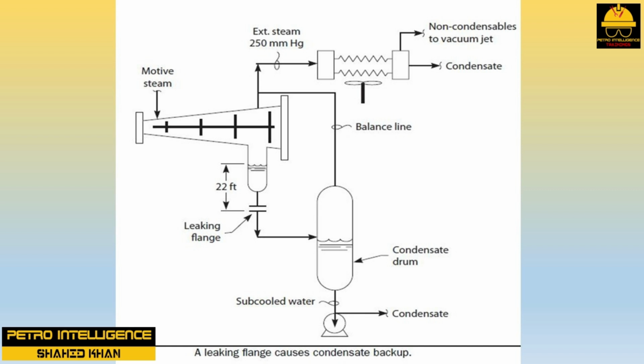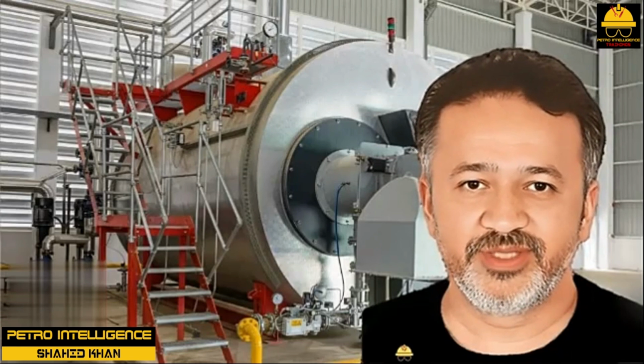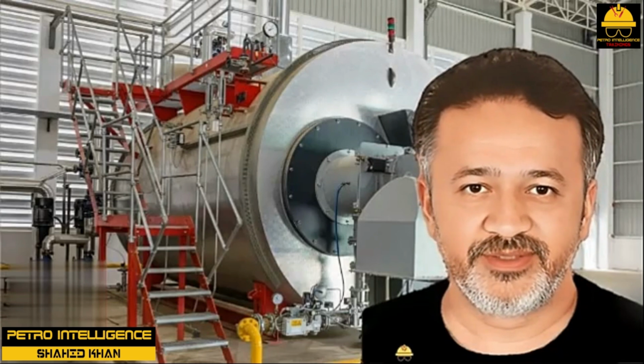The steam required to drive the turbine fell by 18%. This incident is technically quite similar to losing the downcomer seal on a distillation tower tray. Again, it illustrates the sort of field observations one needs to combine with basic technical calculations. This is the optimum way to attack and solve process problems.